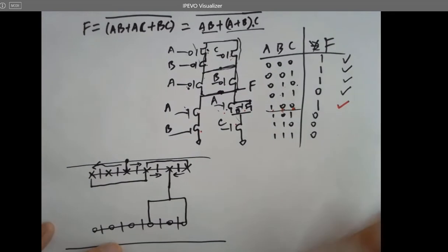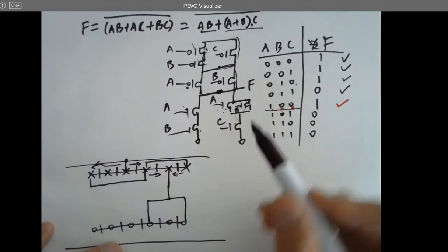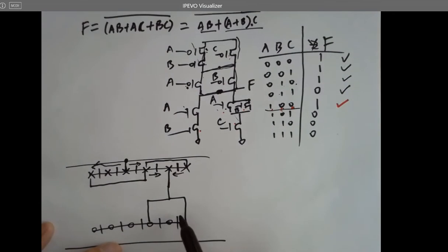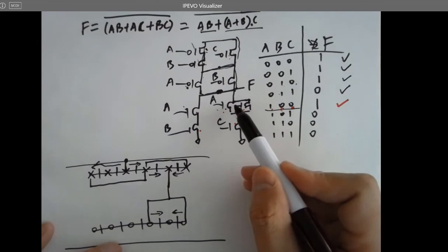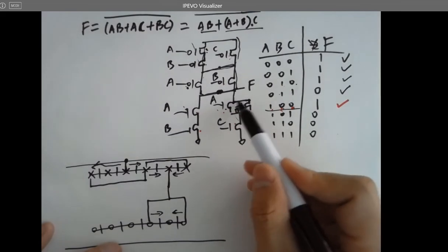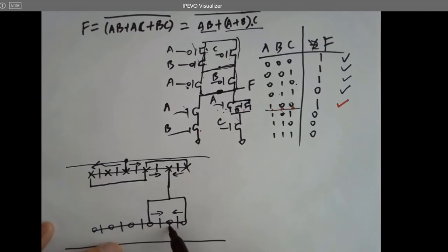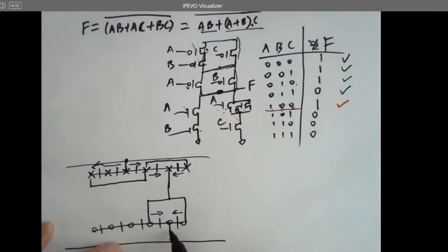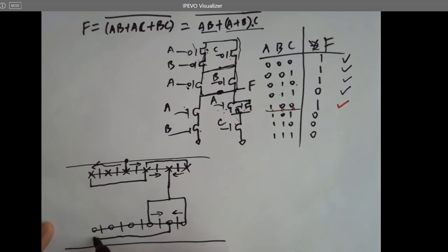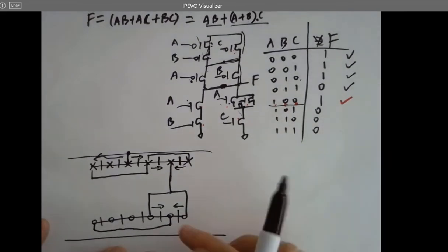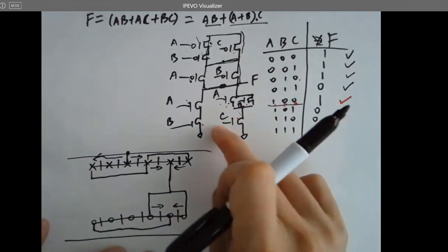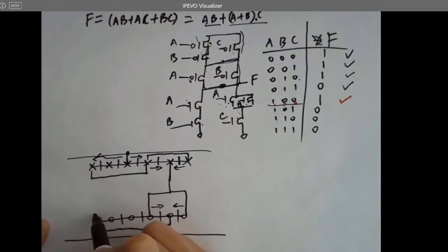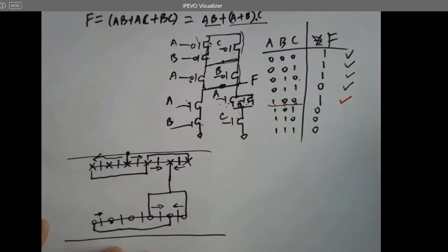So for this node, if I connect to this point, I'm getting 2 parallel NMOSes, which are these 2 guys, right? Parallel NMOSes and merged to this point. And then I need a series NMOS after this point. So what I did is I shorted to here. So merged here and go through this NMOS, go through this NMOS, and this one should go to where?